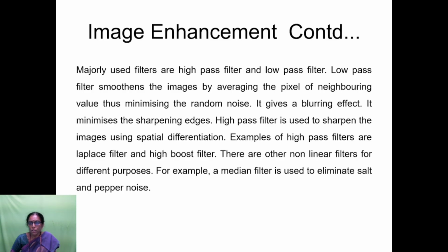High pass filter is used to sharpen the images using spatial differentiation. Examples of high pass filters are the Laplace filter and the high boost filter. There are other nonlinear filters for different purposes. A median filter is used to eliminate salt and pepper noise.